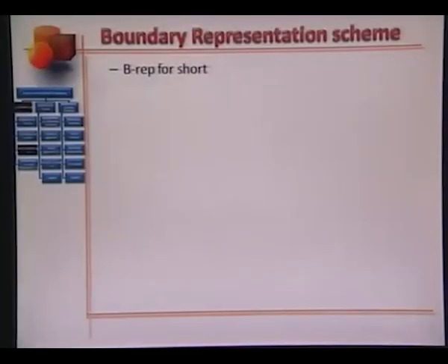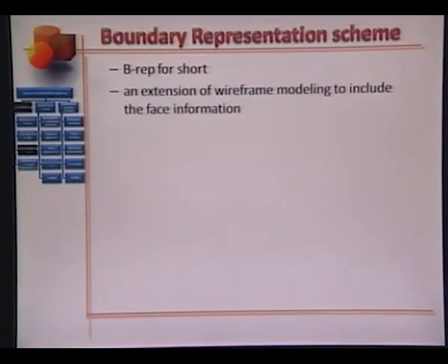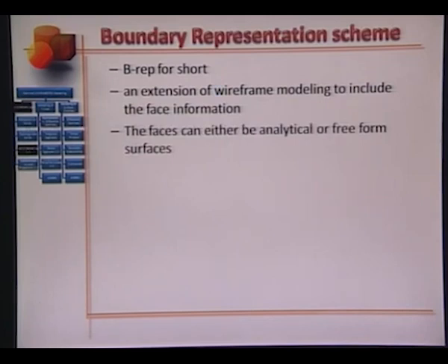The boundary representation scheme takes care of the anomalies in the wireframe approach. This is called BREP for short. The boundary representation scheme is an extension of the wireframe modeling to include the face information. Faces can either be analytical or freeform surfaces.